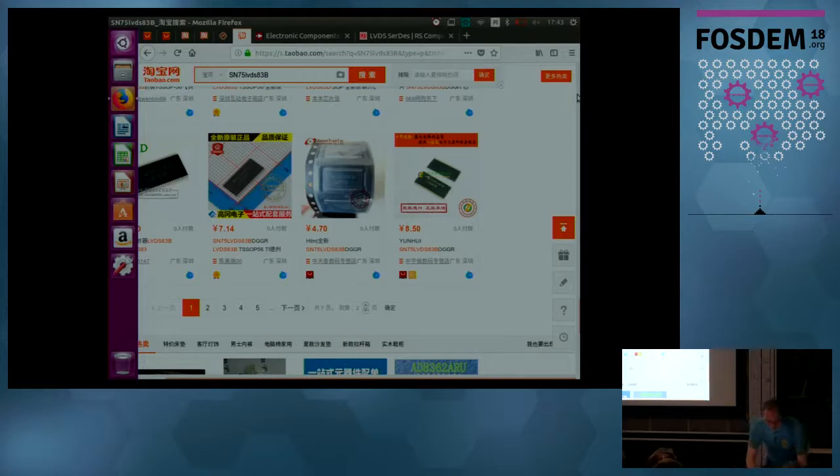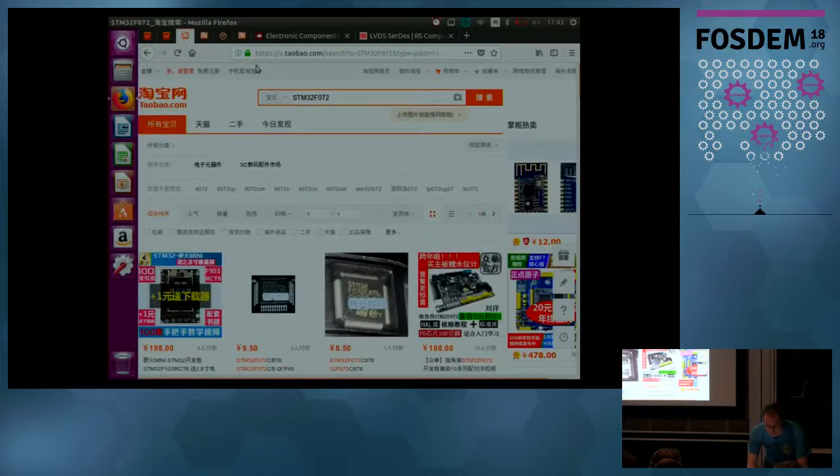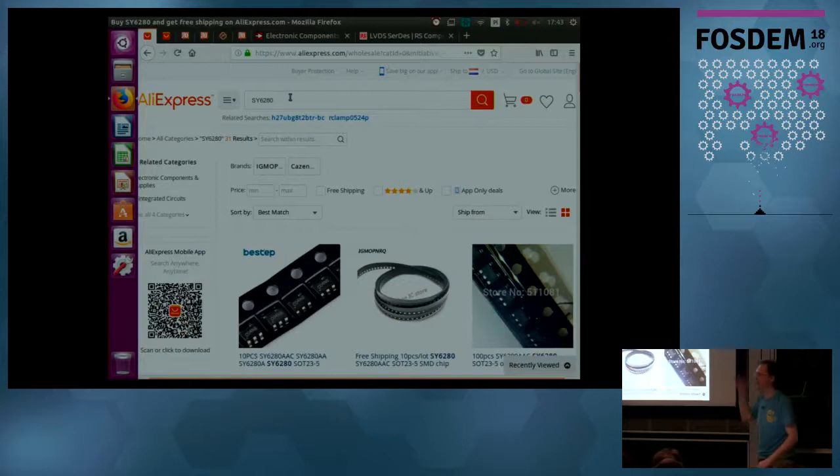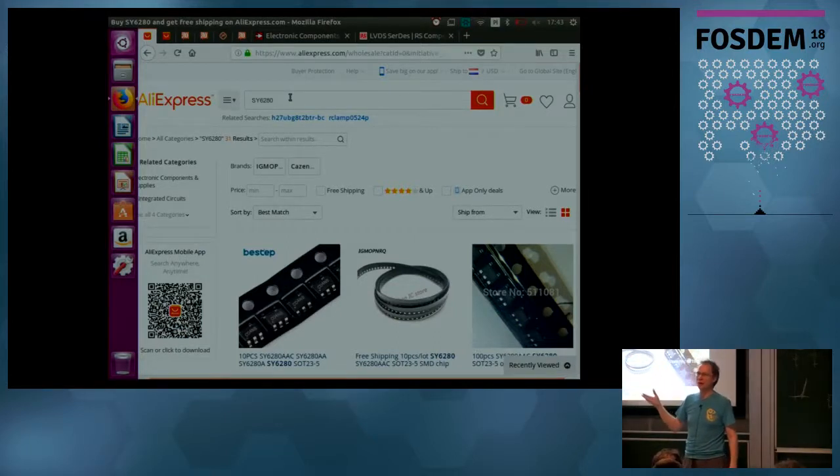The other more popular one, it's very common, for example, for people to use a Texas Instruments or a USA-designed current limiter chip for USB power. In certain circumstances, you can't use the power of the USB hub. You have to do the power check, the current limiting, yourself.